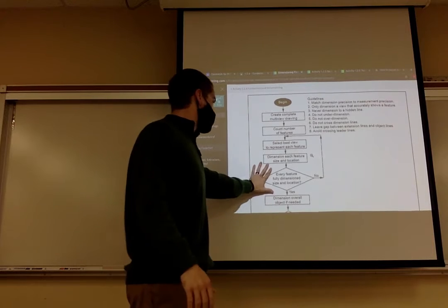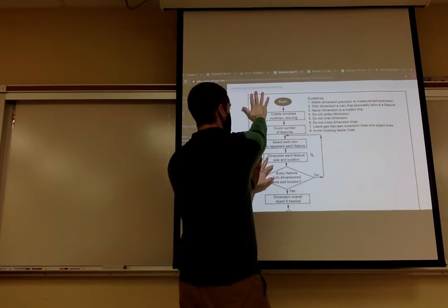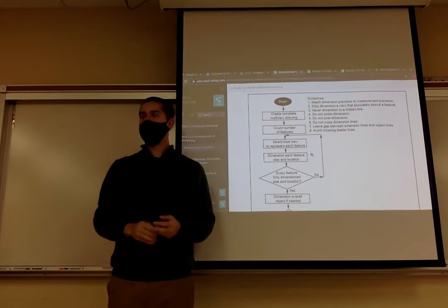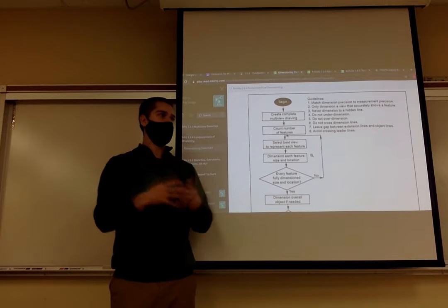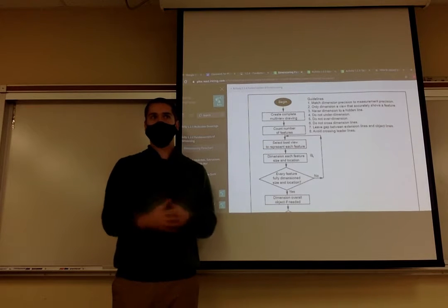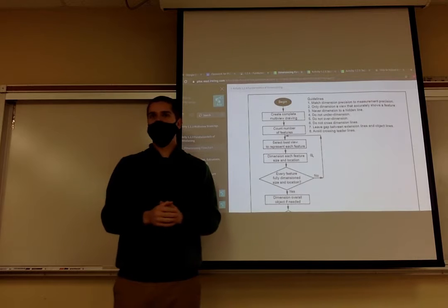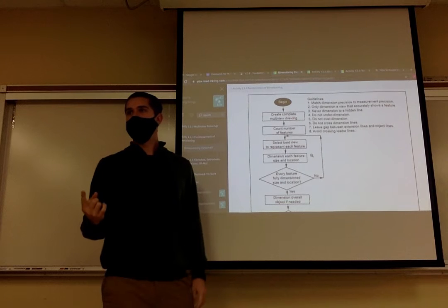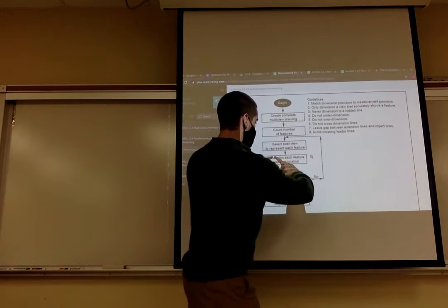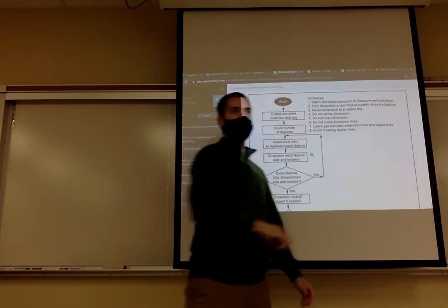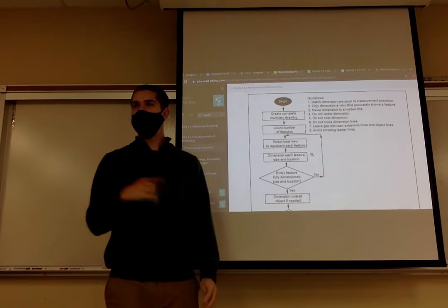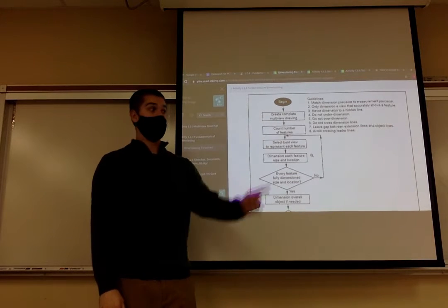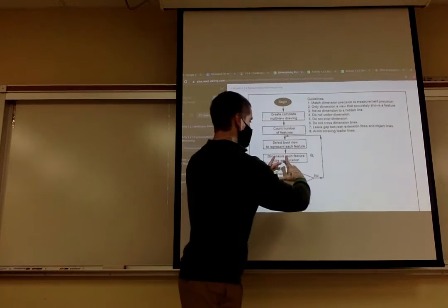When you have your multi-view drawing, you should always have the front view, the right view, the top view, and then the isometric. You never dimension an isometric view. The isometric view is only there to give the best three-dimensional perspective of your object. You only put dimensions on your orthographic views. The trick is, your hole could be visible here, and then you can see the hidden line on the right. Well, which view should you put the dimension for the hole?